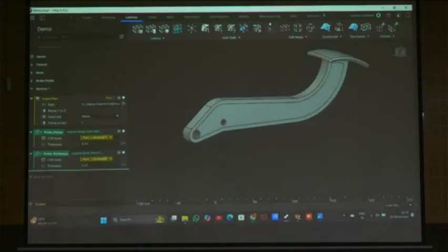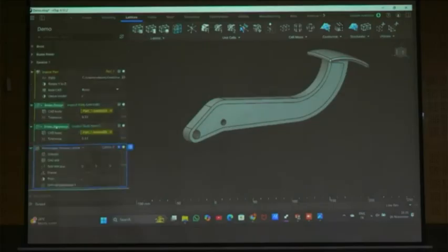Okay, now I will apply the lattice. This is the one I will drag. You tell me which lattice I should apply, whether graph strut based, 2D lattice, or TPMS lattice. In TPMS, which one should I apply? You want to see gyroid, okay, that is TPMS then.